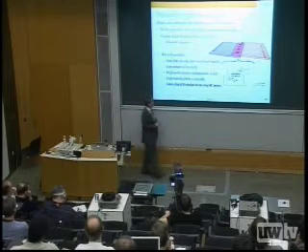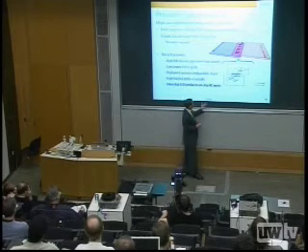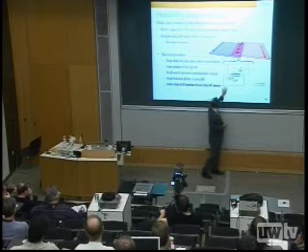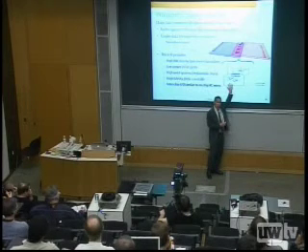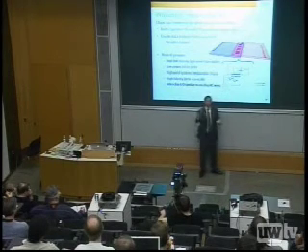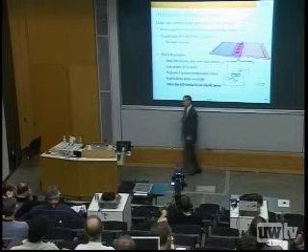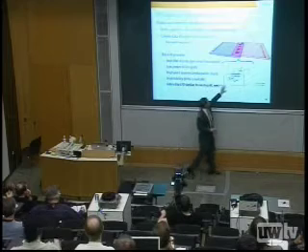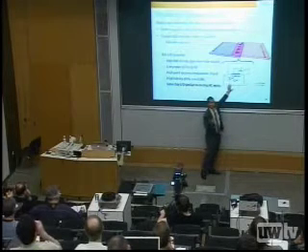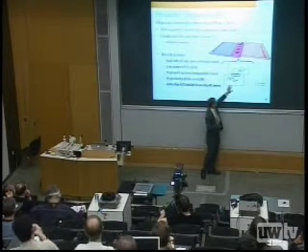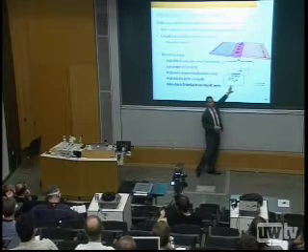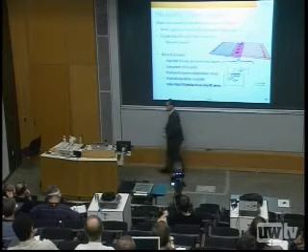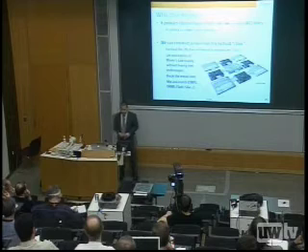energy costs. The systems that I can build out of this could potentially be very high yield, because if a chip is broken or doesn't work or fails, I just pick it up and put a new one on. They're not soldered, they're not glued. And I get essentially chip-to-chip communication that has the costs, the area, the power, the latency, that's very similar to being on chip wires. Okay, so why is this useful?